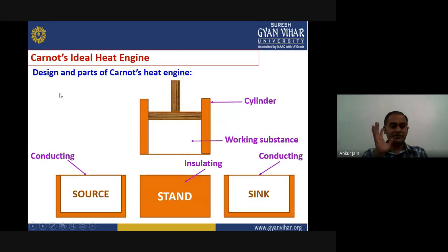We will see in the figure here, this cylinder looks like this, and the walls of this are completely insulating, so that there is no heat loss or heat exchange with the surroundings. The system should be completely isolated from the walls, and this piston is also completely insulated, so the heat cannot be transferred from this part. And again, the second point for the piston is that it should be frictionless. So whenever we move up and down, there should be no loss of energy. This is only ideally possible. That's why we call it an ideal engine.